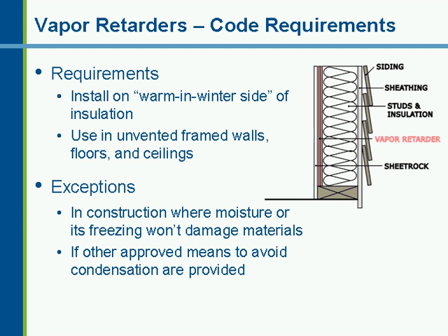Now, vapor retarders. When I talked a little bit before about climate-specific requirements, vapor retarders does somewhat fall under mandatory requirements because you can't trade it off, but it's based on a climate location. So if you're in the climate location that requires you have one, then there is no trading off. It's mandatory. So that's why I had it under the bullets of specific climate requirements.